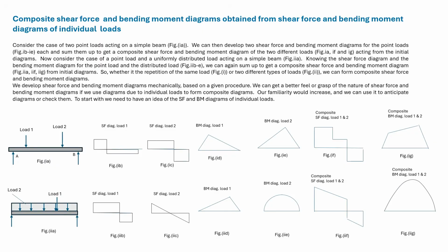Shear force and bending moment diagrams for individual loads acting on the same beam can be added up to give the shear force and bending moment diagram for composite loading. Here we have a beam subjected to 2 point loads.